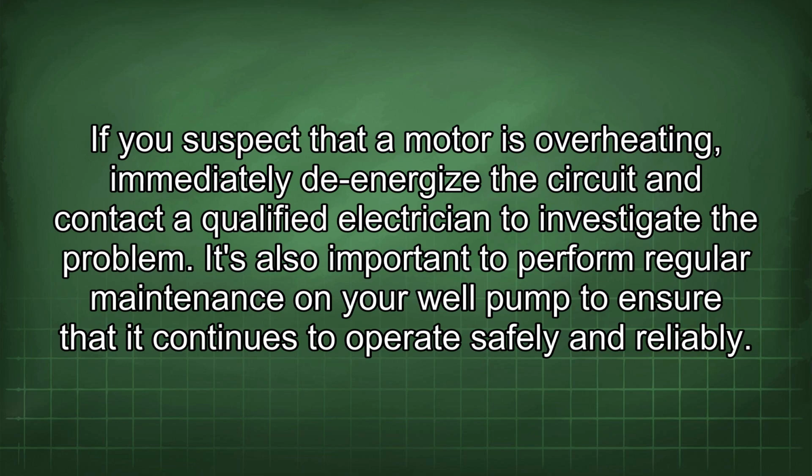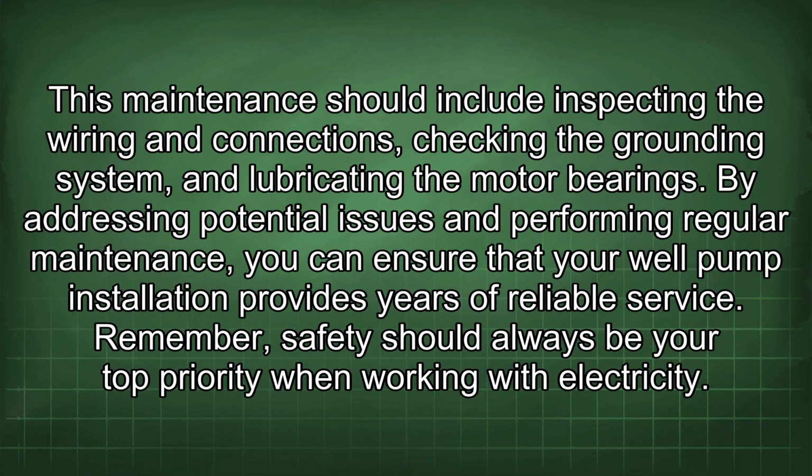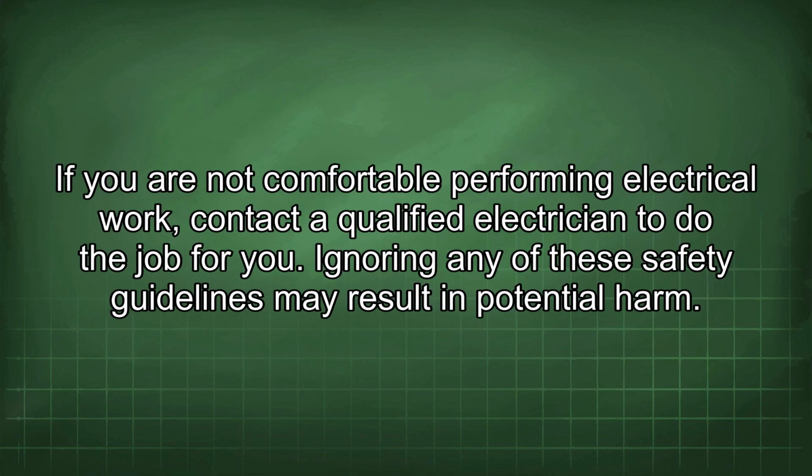It's also important to perform regular maintenance on your well pump to ensure that it continues to operate safely and reliably. This maintenance should include inspecting the wiring and connections, checking the grounding system, and lubricating the motor bearings. By addressing potential issues and performing regular maintenance, you can ensure that your well pump installation provides years of reliable service. Remember, safety should always be your top priority when working with electricity. If you are not comfortable performing electrical work, contact a qualified electrician to do the job for you. Ignoring any of these safety guidelines may result in potential harm.